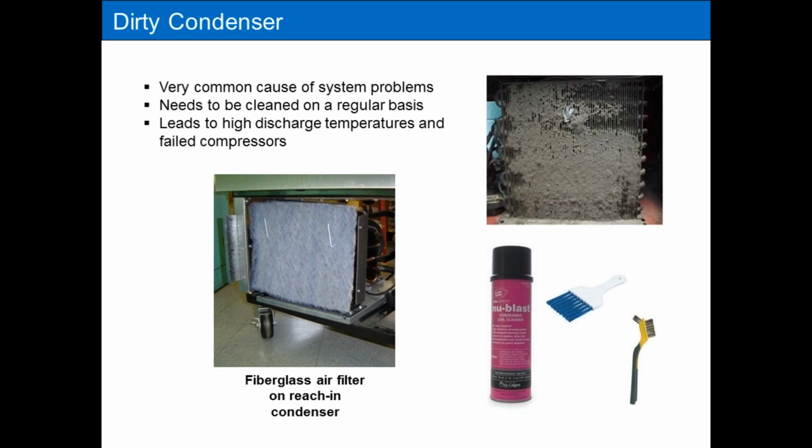You can also use some coil cleaner. They make some really good coil cleaner in a can that is rinseless. You apply it and you don't have to rinse it with water. So you can use that for these condensers, and they're pretty effective. These rinseless chemicals do work well. They even work somewhat okay on grease, depending on how impacted the grease is. But for dirt, they definitely do a good job, and on grease, so-so. I use these rinseless chemicals a lot.